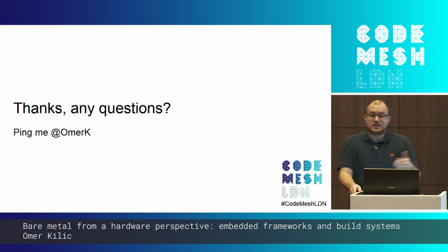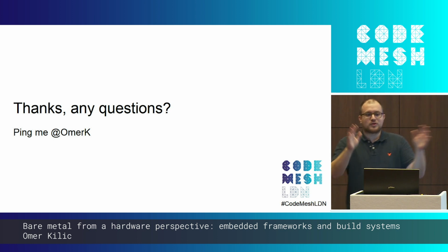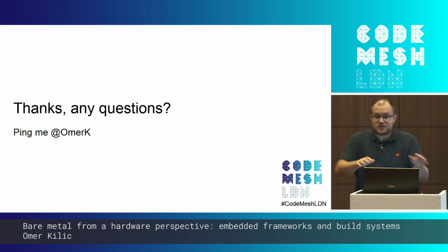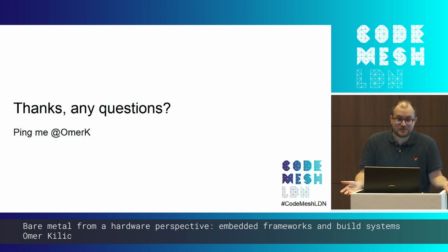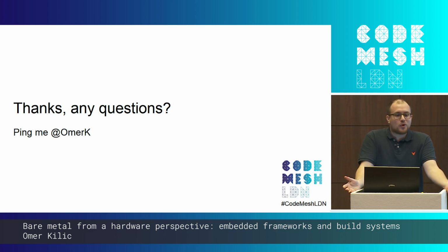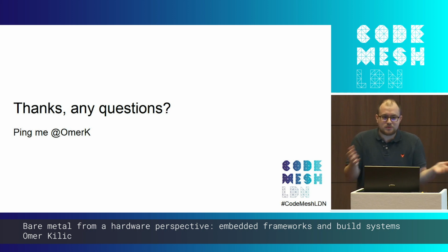What GeoHot is doing is kind of trying to democratize the very expensive stuff that was available to very big corporations, perhaps. But overall, most embedded systems developers, especially ones working on smaller systems, would tell you that printf is the best kind of debugging they have on most systems, which is quite tragic. So trace ports, trace pods, etc. These are all things that probably are the state of the art, if you know what I mean. Again, no great answers, I'm afraid. At least that I know of, anyway.